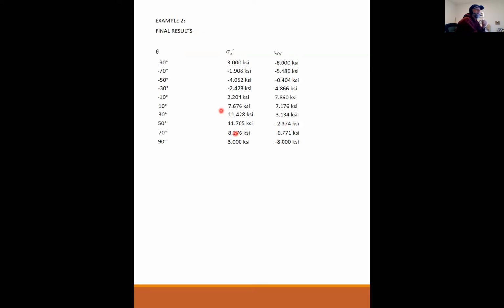So there's a way to calculate, without going through a million iterations, exactly where and what: where being what angle, and what being the magnitude of the principal stresses. And at the same time that you have reached your maximum or minimum stresses, your shearing stresses will be 0.